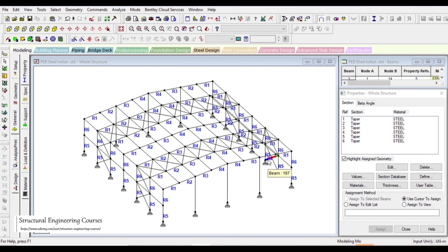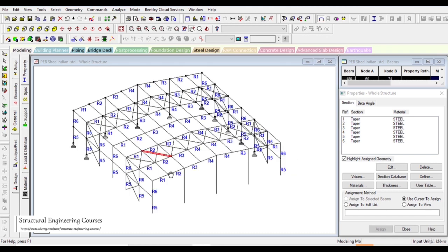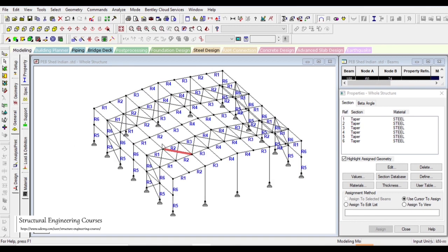So some of the experienced engineers that must be listening to this might not be comfortable with what I am saying. But according to my concepts, we should always provide bracings as either a compression member or a tension member, both, because we shall never know how this structure will behave in an earthquake. The structure may go in a torsional mode, or in a translational mode, or in a linear translational mode. So it's all up to how the earthquake force will strike this structure.